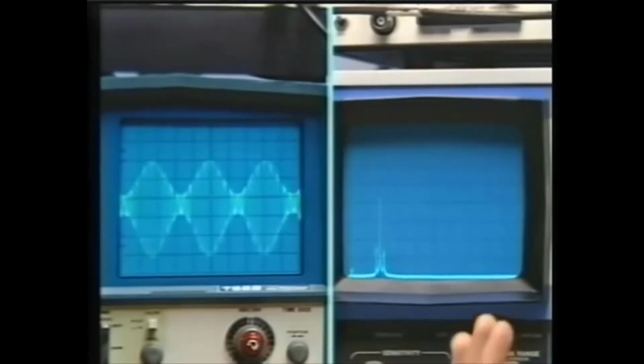This is actually called a ring modulator. It's very simple to multiply a signal by a square wave. It's just a chopping process. And so a square wave carrier signal is very convenient to generate, and then you simply filter out the higher order harmonics. Right, I'll go back to the scale that we had before.